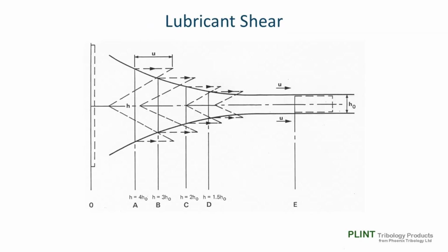This figure shows the velocity profile of a lubricant approaching an elastohydrodynamic rolling contact of the type generated in a two-roller machine. The fluid in contact with the moving surfaces necessarily travels with the surface velocity u. Considerations of continuity suggest successive velocity profiles as the fluid approaches the contact of the form shown in the sketch.